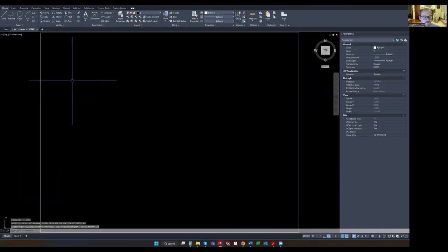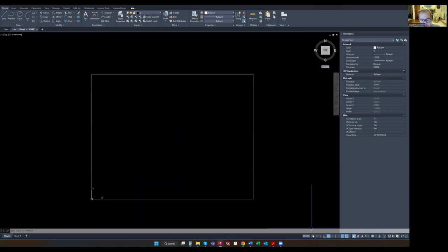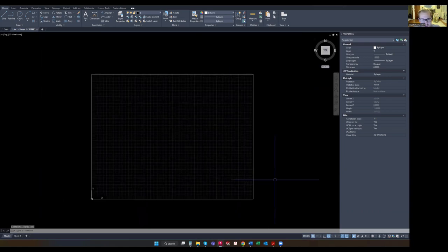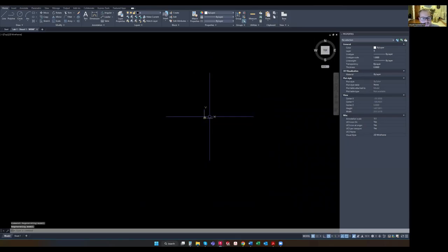So go ahead and get yourself zoom extents, double click the middle mouse wheel to get the rectangle that we created yesterday front and center for you. You can even zoom out just a little bit. I'll go ahead and turn my grid back on in this view, just because remember we set those limits yesterday. So this just gives you a little bit more of a nice foundation of where we're actually going to be drawing here in this infinite space.